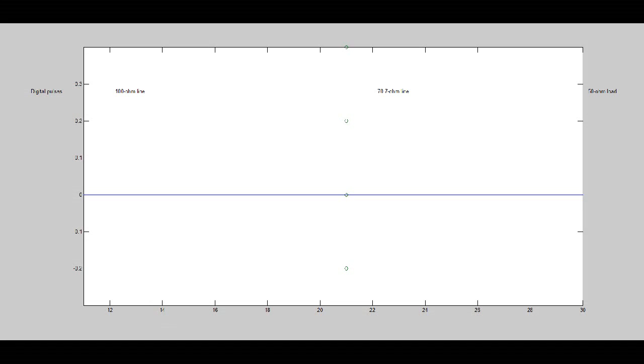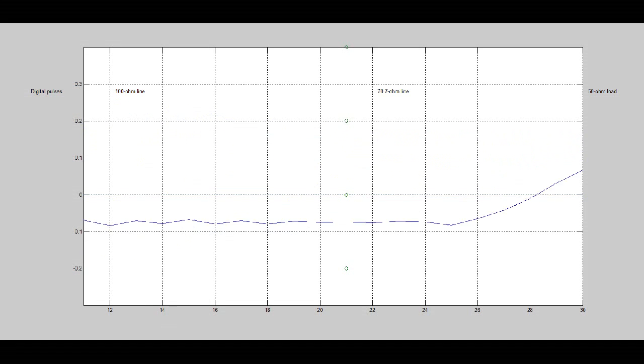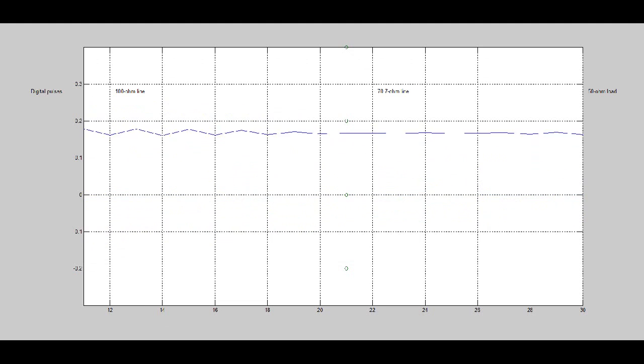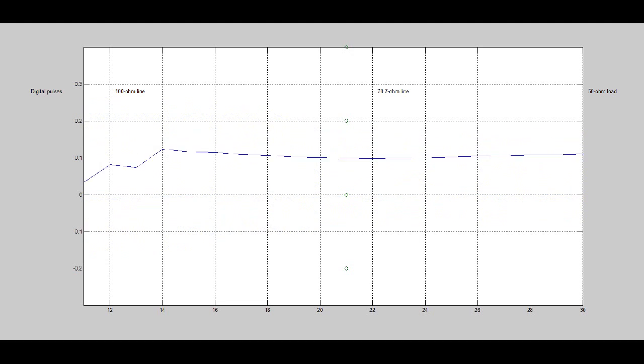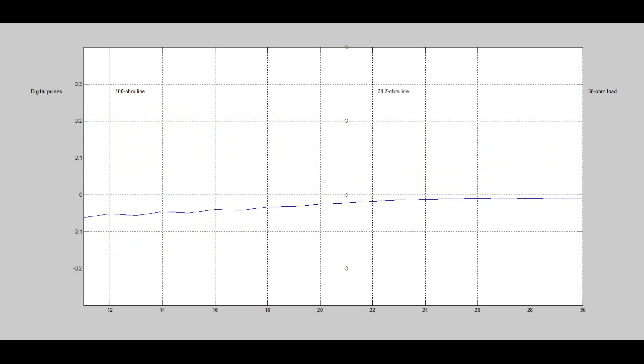This is a more realistic cable, around 10 meters long. With the shorter cable, we have less ripple. The voltage doesn't go up and down cleanly, but it doesn't bounce around as much either. But the signal is still bad enough that the line could have glitches. The line would have to be even shorter to eliminate the bounces entirely.